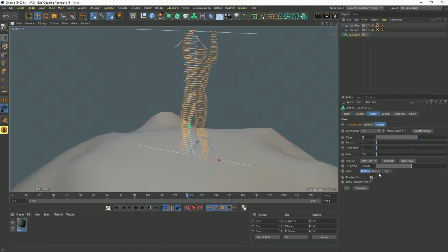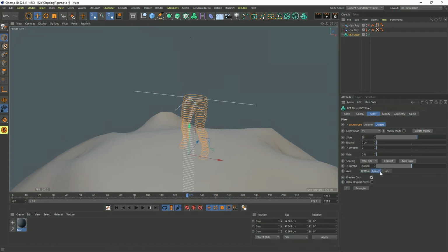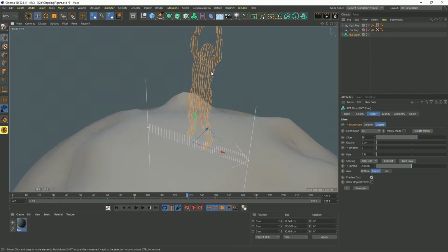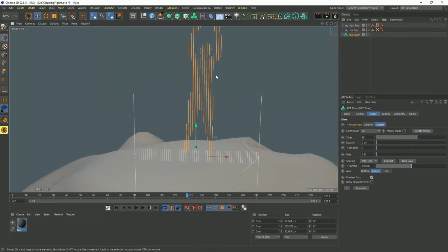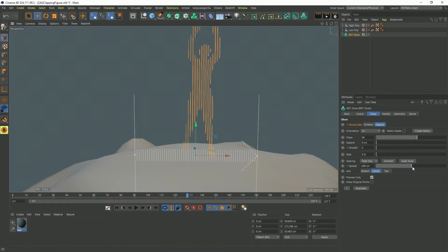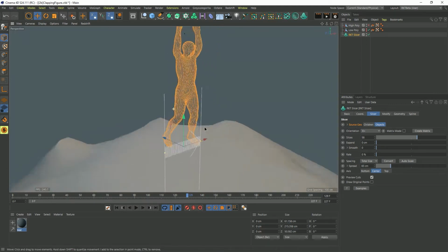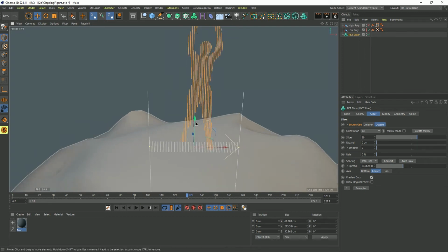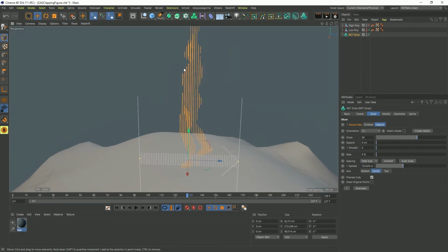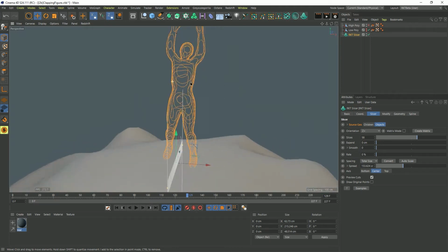So what do we got? Orientation. Like I said, I want that to be from center, sorry. So orientation, change that to X plus. So instead of going up on Y, we're now slicing on the X axis. You can see a bunch of almost vertical slices here from the front, but go to the side, you see how it's all chopped up in that orientation. We can, of course, change the spread and have those be a little bit tighter and get to see more of the cuts, or we can spread them out more. Changing the orientation to Z plus, we can slice front to back and get cuts that way and get a completely different look on the figure.